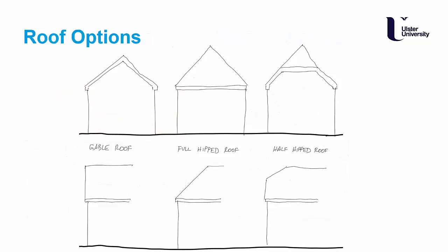One other aspect that people do find a little bit difficult is just how to show the roof. So try and think of it in 3 dimensions. Have a look at different houses around you and the arrangement of the roof. What was shown on the elevations was what is called a gable end roof. So in this case here, the brickwork is built right up, and you have this triangle that sits on top of the main part of the masonry construction, and the brickwork carries right up. So on the front elevation, on the rear elevation, the roof will overhang a little bit, and the brickwork will continue up that line. It's just hidden in behind the roof on the front there.